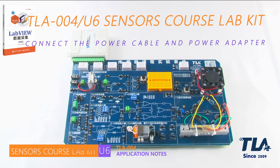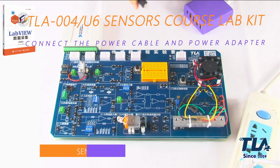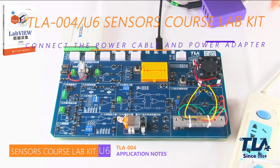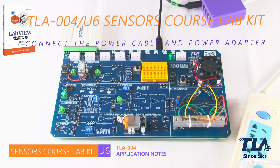Next, find the dual Type-C cable and Type-C port power adapter in the package. Insert the plug at either end of the dual Type-C cable into the Type-C socket on the outer side of the middle and upper part of the kit board. Insert the plug at the other end of the dual Type-C cable into the power adapter of Type-C port. Plug the Type-C port power adapter into the main socket. Turn on the main socket switch.